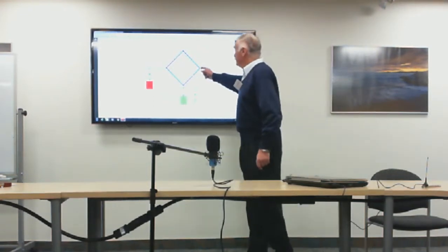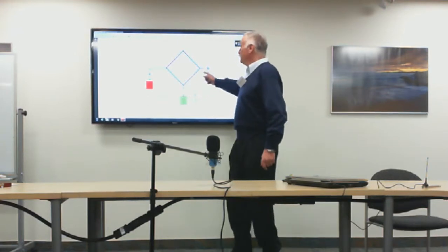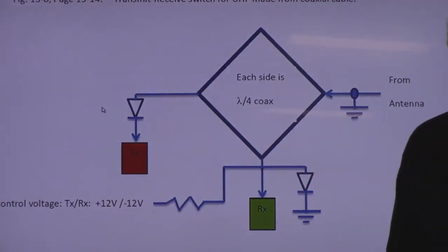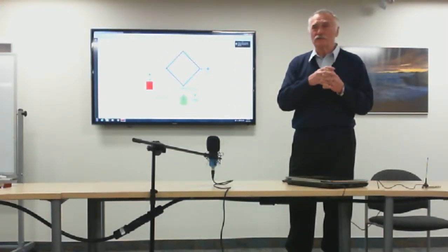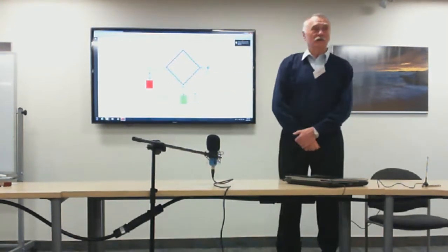So whatever comes down from the antenna over a 1/4 wavelength section will be in phase with the signal traveling the longer 3/4 wavelengths. So the two signals in phase, they do combine, you have reception in your receiver.